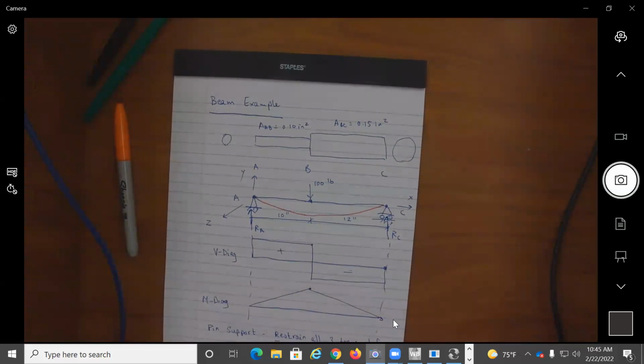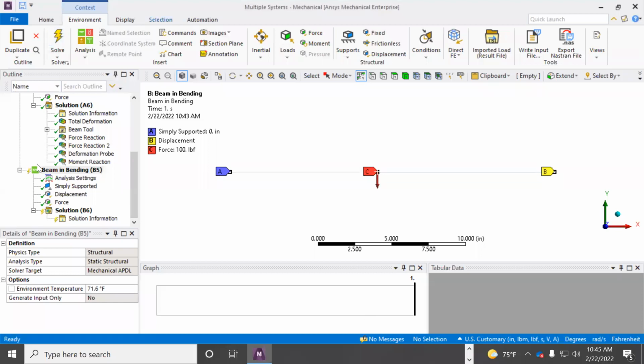Now, I do not have any torque applied. So we need to have like a workaround. Really, we do not have anything to prevent the beam from rotation. We know it's not going to rotate. But numerically, we want to add a virtual support. Should there be any torque, it's going to prevent the beam from spinning. Okay. In order to demonstrate this, let me try to run this problem here and see what we're going to get.